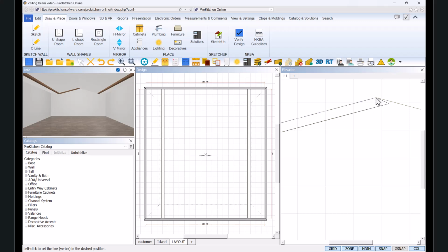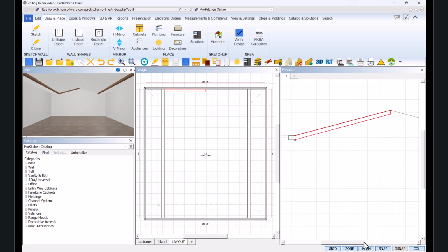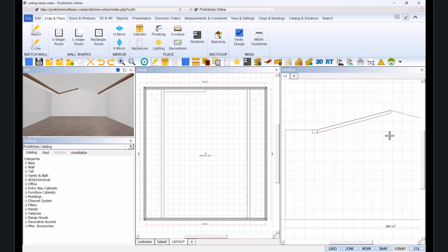Then left-click to secure. Next, hover to the lower point, left-click once, then move the mouse so the point sits below the cathedral peak, doing your best to maintain a consistent angle. When the edge displays as vertical, left-click again to secure. Once you are satisfied with the shape, tap the Escape key to release the Edit tool.